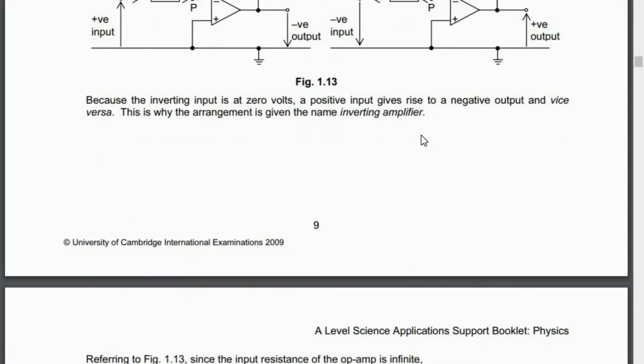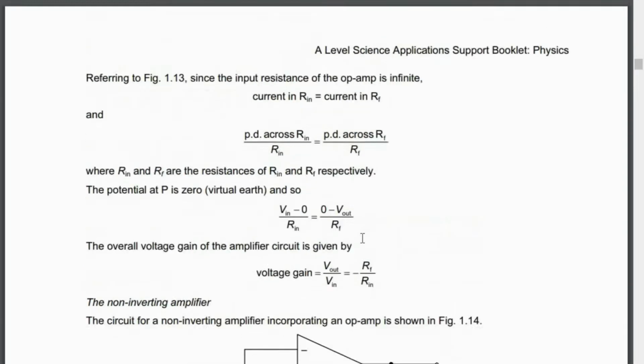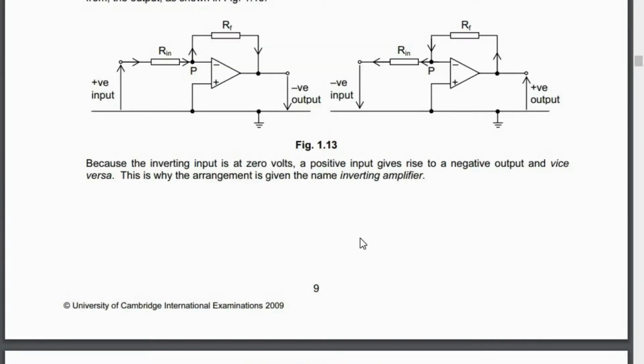So this is no longer an infinite gain. Understand? When it's closed loop, it is determined by the resistance of the feedback loop and other resistors. So that has a finite value, and this can be found. It could be 3, it could be 5, it could be 10, doesn't really matter. Does this make sense to everyone? Alright, so this is it. This is the concept of an inverting amplifier. Is everyone clear on this? Alright, let's move on. They're all negative feedback loops.